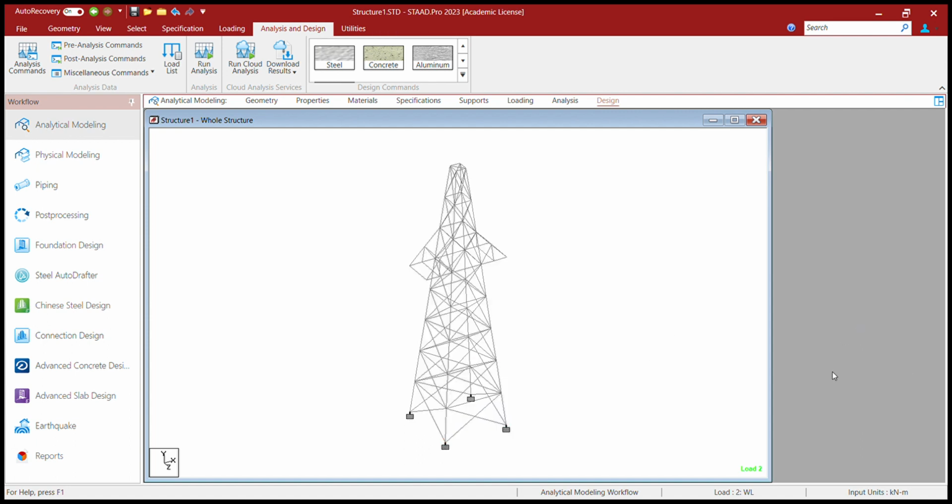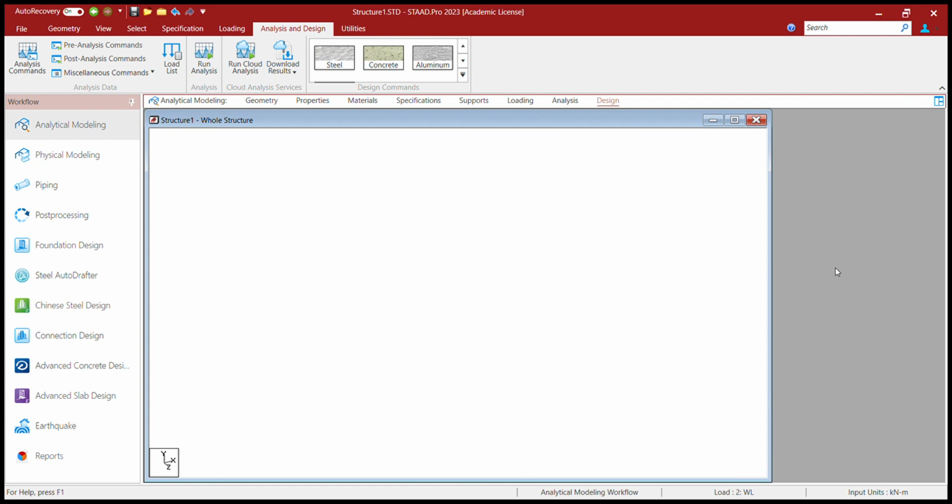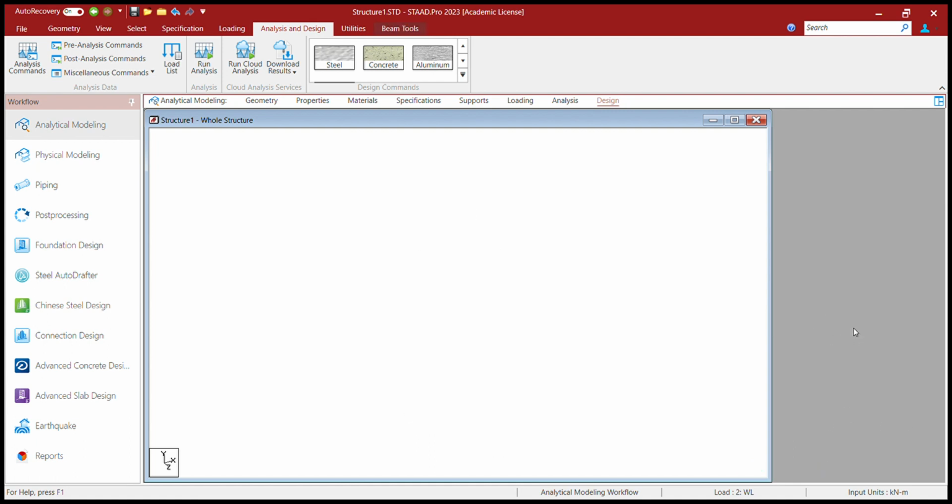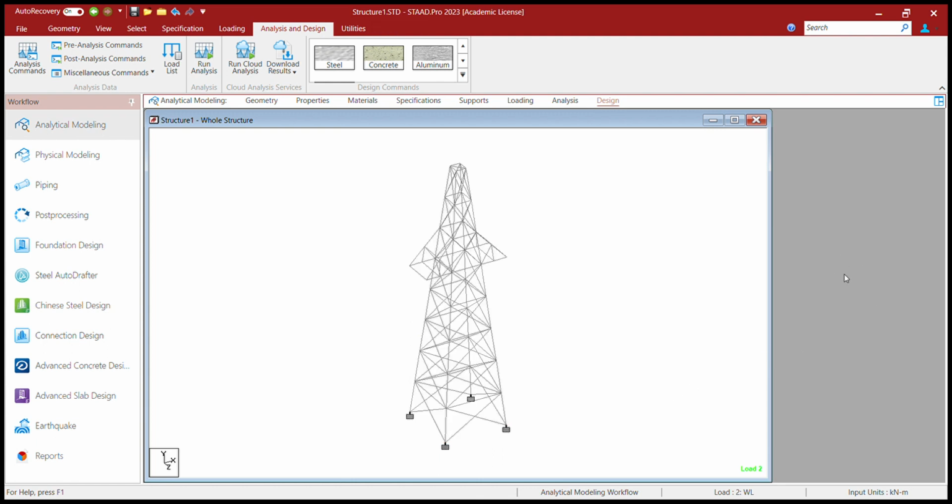Okay. Now in commands, use check code, member takeoff and steel takeoff. Just add these 3 points and assign it to total structure. Okay. Assign to view, yes. Steel takeoff, assign to view, assign yes. Okay, so all properties are assigned. Now simply run the analysis.